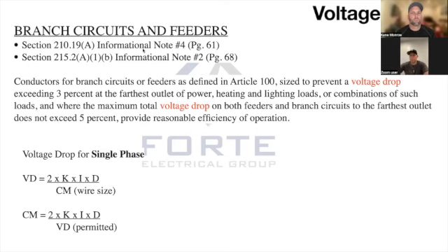But if you are to get engineered plans or start building stuff according to the engineer, they always throw it back on us to do voltage drop to make sure everything's good. Or if you go in and start adding more outlets to a circuit, as a journeyman, you need to do the voltage drop on it just to make sure you don't have to upsize some wiring, some conductors, and go from there.